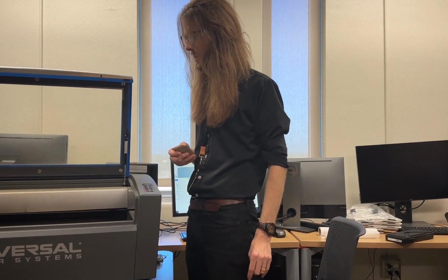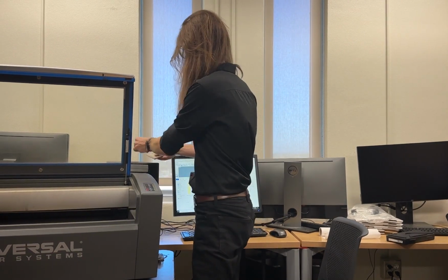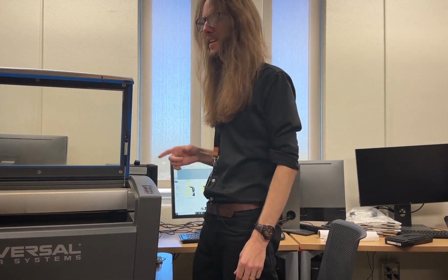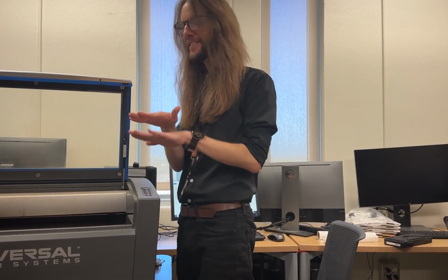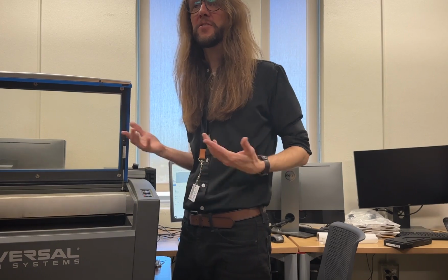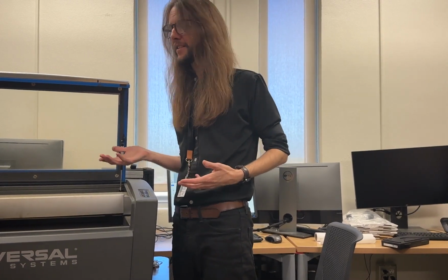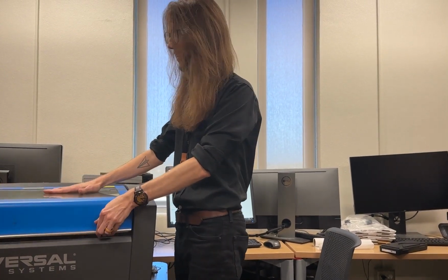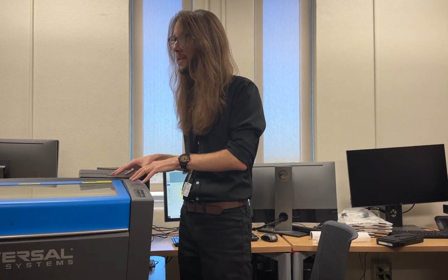I also have no idea how we'll cut it without that piece, which is probably why he was saying, you know, it wasn't cutting at first until I started doing something, and I think I know what he was doing. He was messing with the Z-axis, which is very dangerous. You can start a fire with this machine. It's very easy to do, which is why there's actually a glass piece right here. It's maybe one of the first rules I should say about laser cutting is while you're laser cutting, somebody needs to be in the room, right?